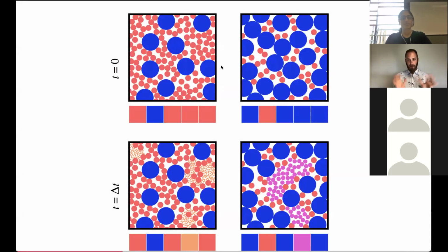So we've got a couple of situations here. One is that we've just got a few large particles and lots of small particles. And you can see here when we're in this kind of situation, these large particles have actually got a lot of small particles touching them. And so when you apply a lot of stress here, we've got lots of little forces all being applied all the way around this large particle. And it's actually quite snug there. So it's quite hard to crack it in half when it's being squeezed concentrically from all the directions.